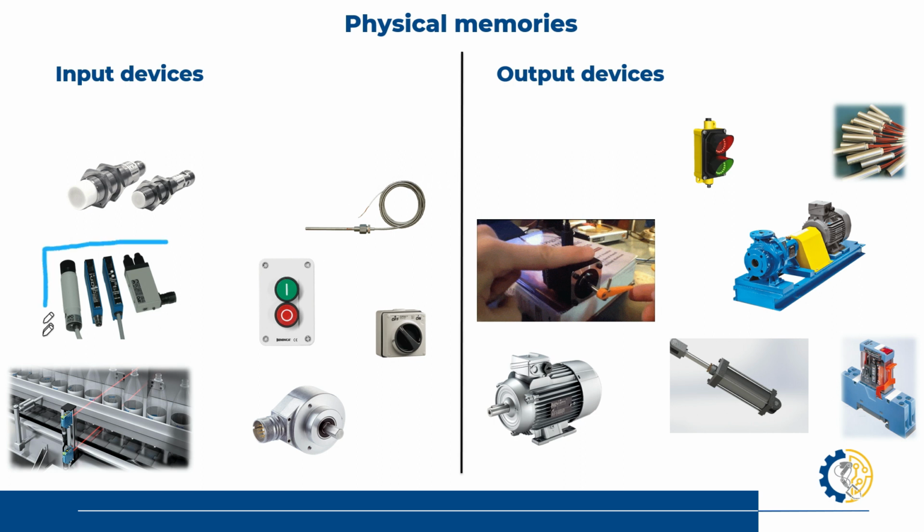So sensors, zeros and ones for a data type. For a button, it's either on or off, zeros and ones, Boolean. Selector, I'm either activated or deactivated, zeros and ones, Boolean. The encoder, there are some encoders that, if you read or assign data without decimals, then these would be double integers.